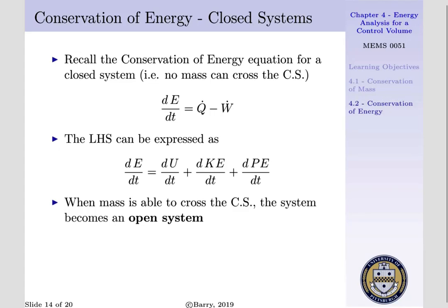Let us now look at the conservation of energy equation. Recall, for a closed system, our change of energy within our system is equal to our heat supplied less our work done. And this can be evaluated on a per time basis, i.e. as a rate.